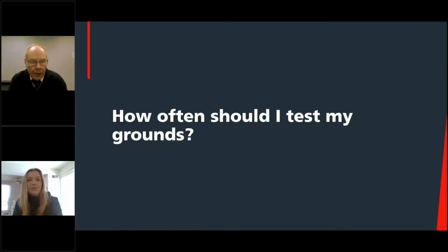Okay, how often should I test my grounds? All right, now the main thing to avoid here, this is pretty much your call, and it has to do largely with the environment that you're in. So if you're in Florida, you probably want to do quite a bit of testing because they get so much lightning down there. And keep in mind that your electrode can do its job, and it can destruct underground in the process of fault clearance.